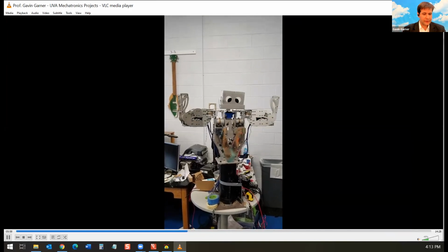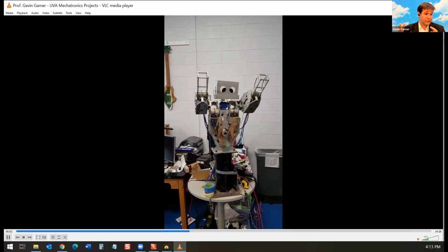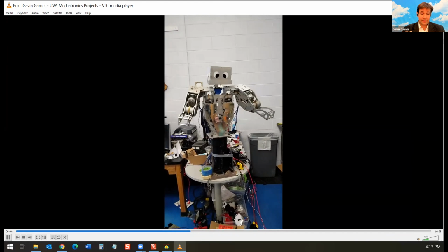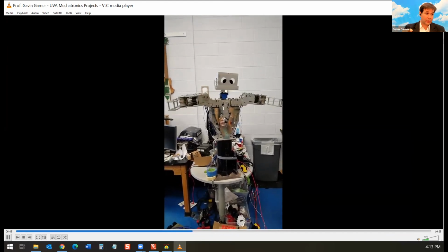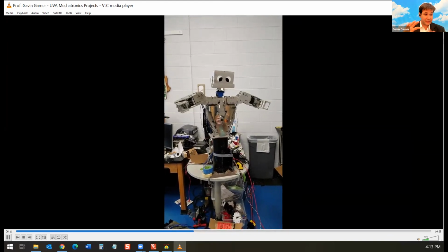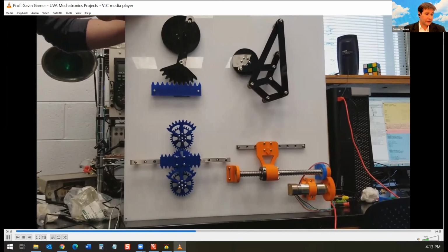So they're not cheap, but they act just like stepper motors, even though they're DC brushless servo motors with absolute encoders inside them. So you can send them just a high or low to tell them what direction to go, and then just send them one pulse, and they'll make a step. But really, it's got all the benefits of a closed-loop feedback control inside of these servos.